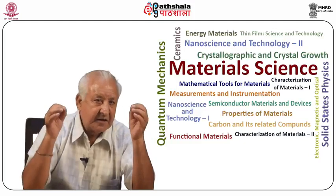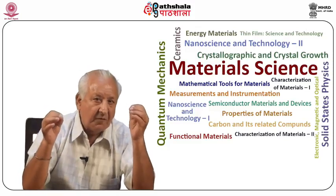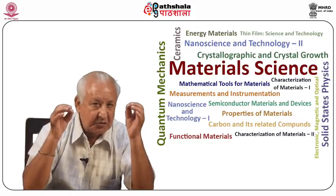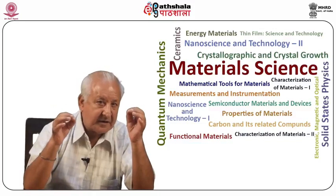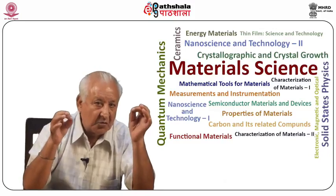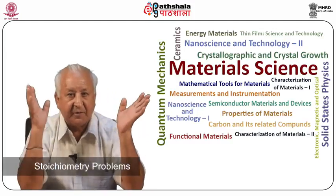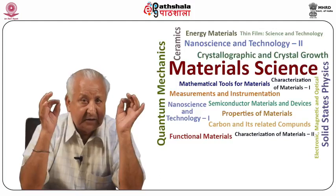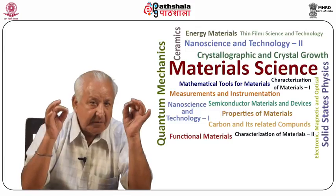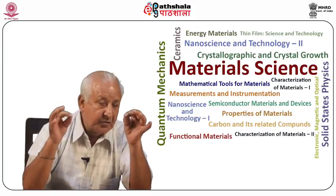It, however, introduces several additional problems. One of the main problems is the addition of a second liquid layer above the first. If the encapsulant is too thick, it will act as a thermal blanket, thereby making growth more difficult. If it is too thin, it will not be able to hold the volatile component, which is likely to result in melt stoichiometry problems. In this technique, the crystal has to be pulled through the encapsulant layer. There is every danger of improper draining of the encapsulant from the crystal, thus causing cracking during cool down.